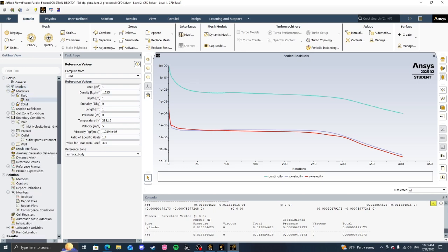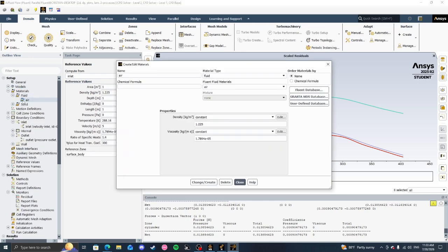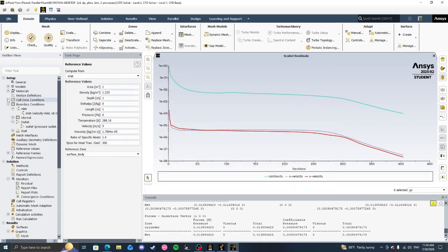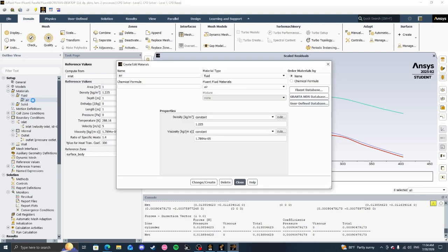We are going to go to laminar, click OK, make sure the model's laminar. And we're going to keep the air properties just like that. We aren't going to change anything. Make sure when you're doing your process, you solve for the Reynolds number to make sure it's accurate over the cylinder, rho V D over mu. This is your dynamic viscosity, not kinematic. Excuse me. I'm going to keep track of those, but it should be air.